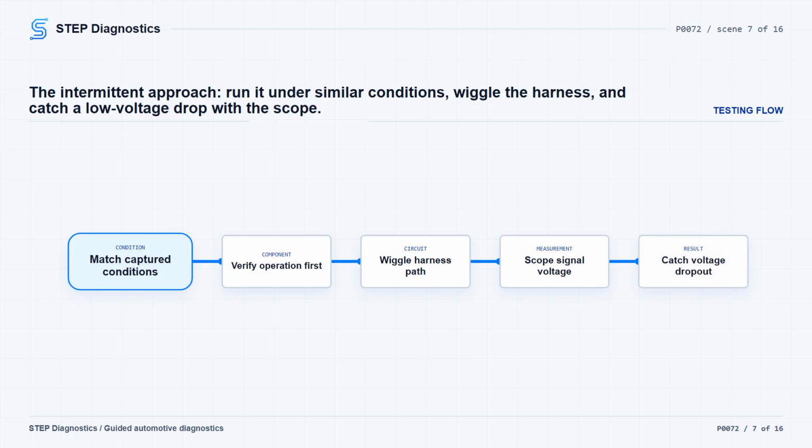Check the battery or batteries for proper charge and operation. Verify related chassis grounds, and inspect the component, module, and inline connectors for locked connectors and terminal damage. If you are using a scope, back probe the temp sensor signal circuit and monitor voltage during the wiggle test.